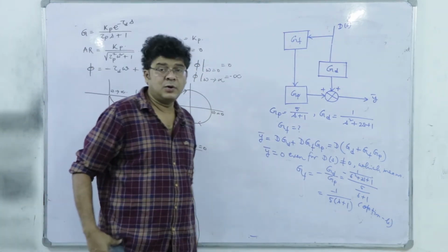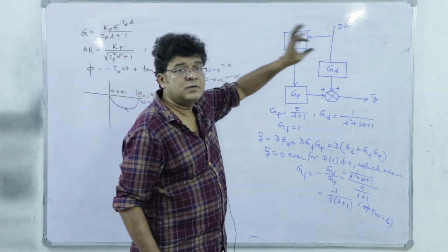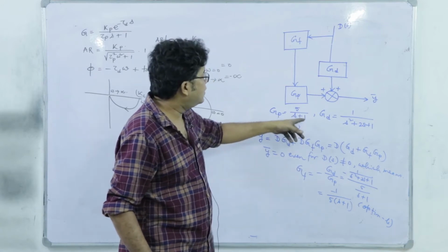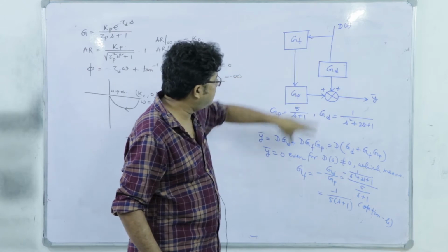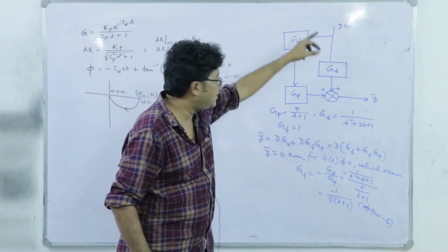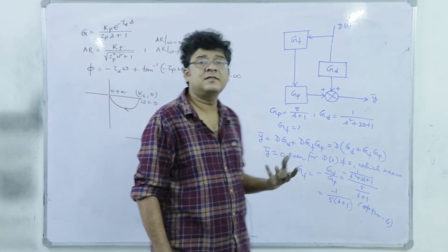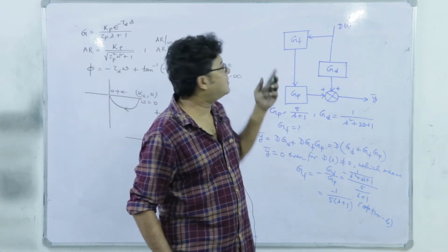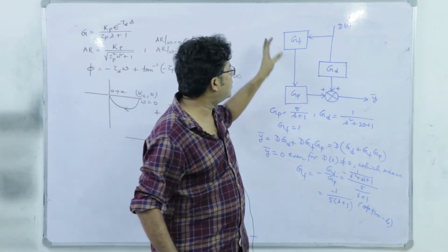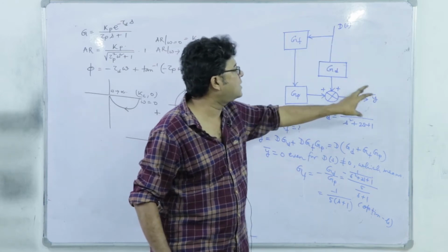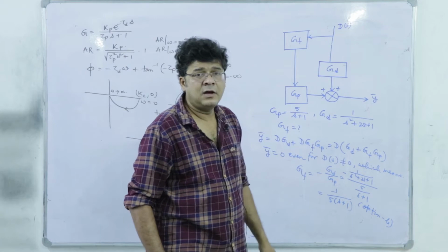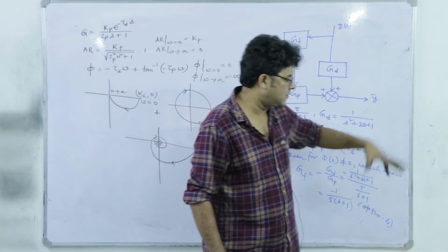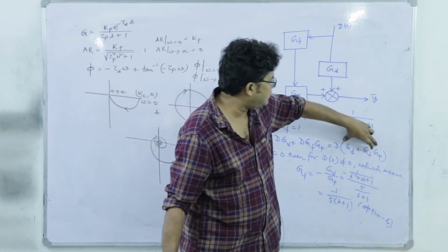So, what is important to note here, we should not use the feed forward formula of GSP or GC directly. We have to use the block diagram, we should write this Y and D relation, and therefrom we must understand the logic of this feed forward entire loop, that as it is typically a servo mode of control, we do not have any set point. So, disturbance must not affect this Y. So, Y or the deviation of Y must be always 0. So, Y and D's transfer function, the intermediate transfer function, which is this block itself, must be 0.